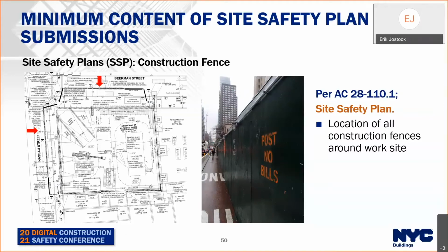There are 2 exceptions where chain link is permitted. Stalled sites, and 1, 2, 3 family buildings or commercial buildings 40 feet or less in height, set back at least 15 feet from sidewalks or spaces accessible to the public, and 5 feet from adjacent buildings or structures.